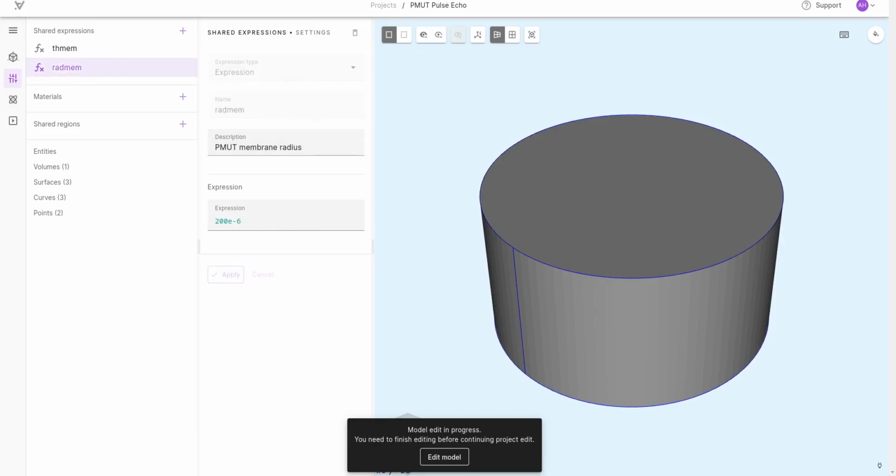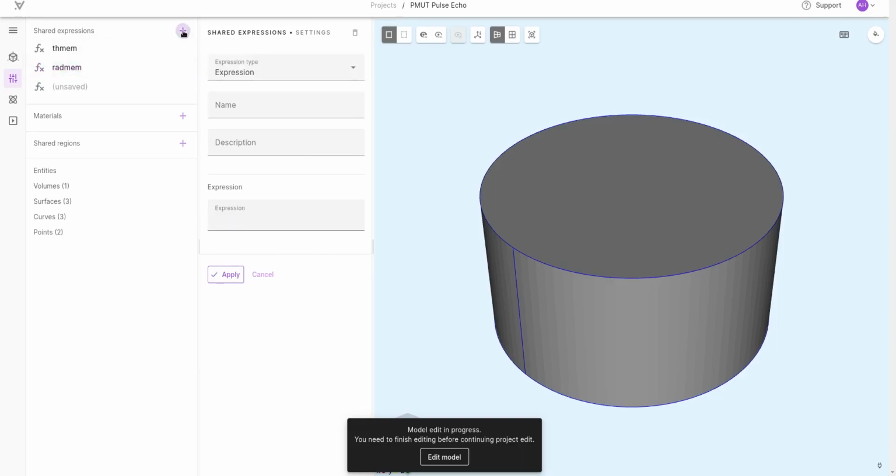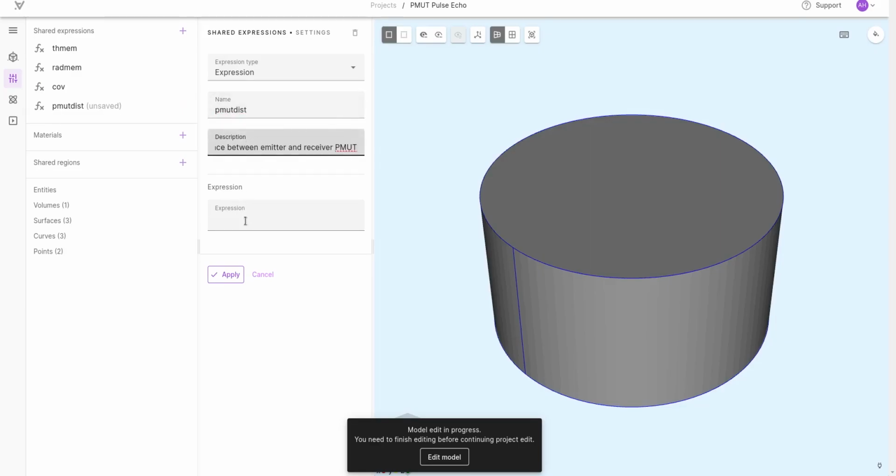Then, as you might know, you have to have some coverage of the piezoelectric electrode. It shouldn't cover the whole membrane. Typically the optimal actuation is around 2/3 coverage in radius. So that's it. Then we also want to parameterize the PMUT distance, so they will be top-down facing, and they will be at a distance of 5 millimeters.